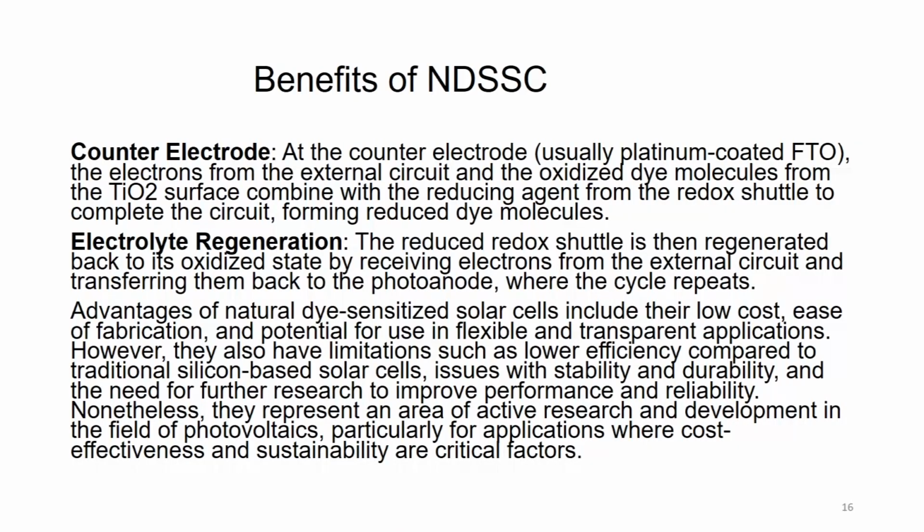Advantages of using natural dye sensitized solar cells include their low cost, ease of fabrication, and potential for use in flexible and transparent applications. However, they also have limitations such as low efficiency compared to the traditional silicon based solar cells, issues with stability and durability, and the need for further research to improve performance and reliability. Nevertheless, they represent an area of active research and development in the field of photovoltaics, particularly for applications where cost effectiveness and sustainability are critical factors.